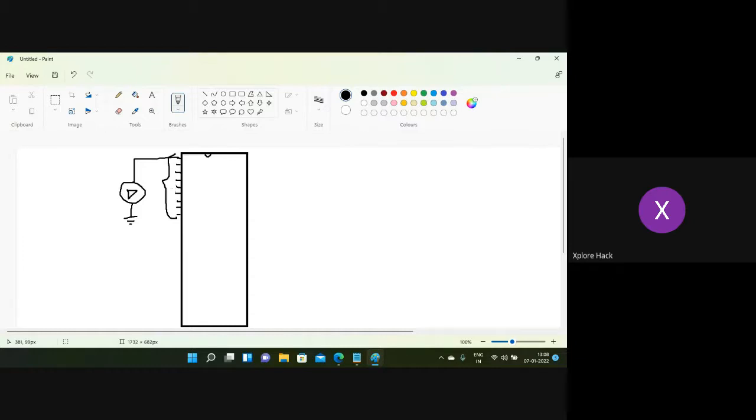The software will take care of that. So if you write the program, after the successful execution of the program, your software will convert the program into machine understandable code, and the format may be binary or octal or hexadecimal. Most of the embedded software will convert the embedded C program into hex file format.